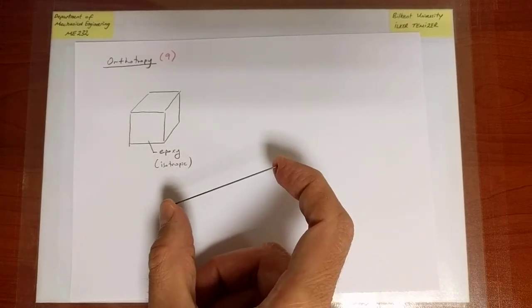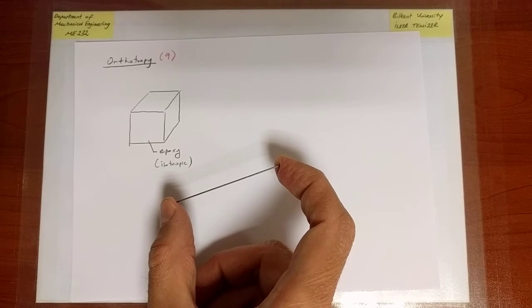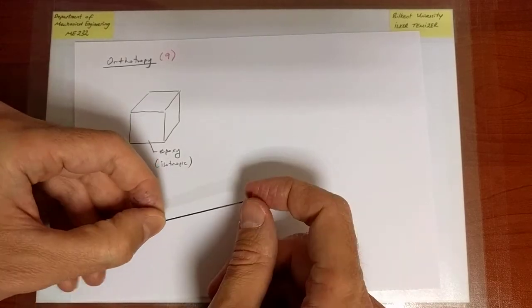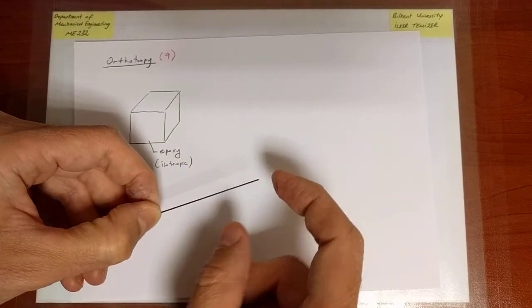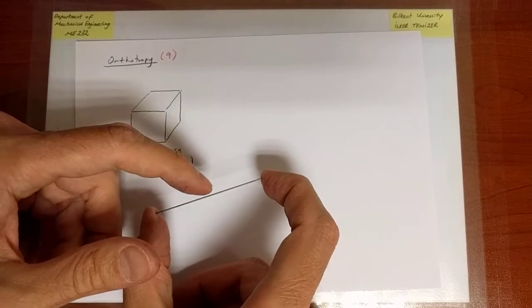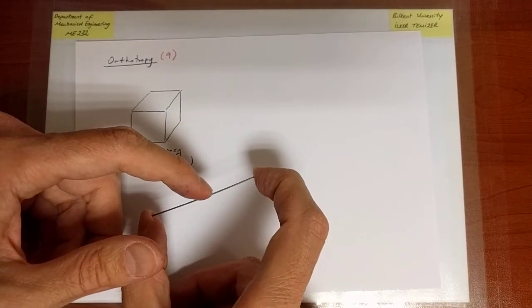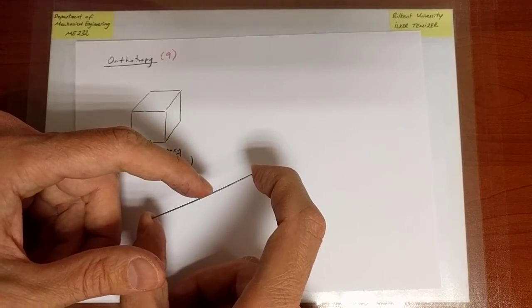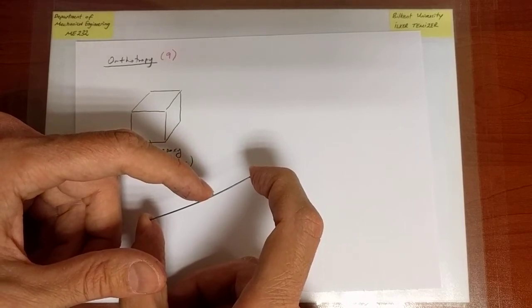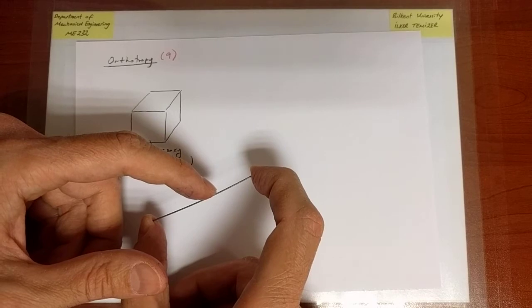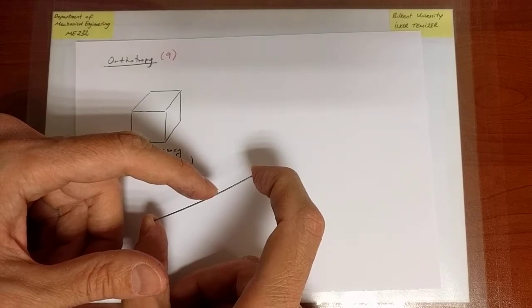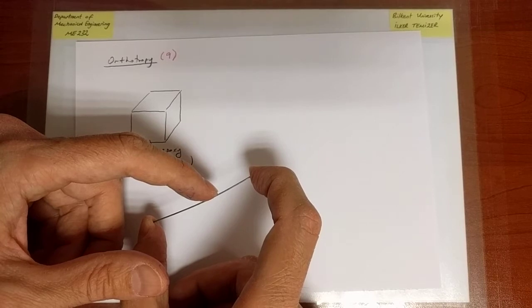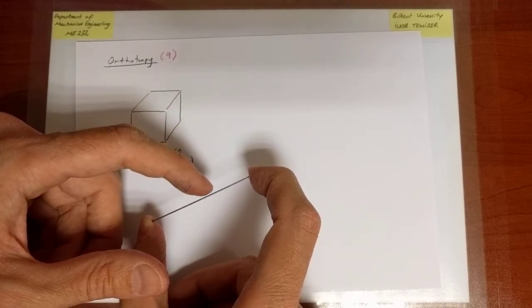And now, if I try to pull on it, then it can carry a large amount of load actually. But if I try to compress it, it's very sensitive, because the very slight amount of imperfection you might put into the structure will cause it to technically buckle, which is a concept that is eventually covered in ME 231. It will buckle, in other words, it will quickly bend out of shape under compression, typically all the way to failure.